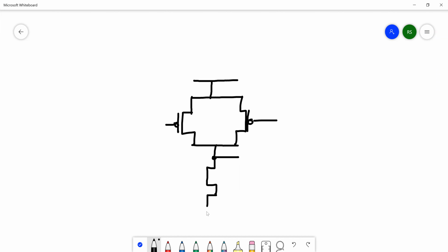If you look at this 2-input gate, for the pull down network, there are a total of 2 capacitances. One is the load capacitance, or what we call CL, which is the sum of the diffusion capacitances connected to the output and maybe some other gate capacitance. And one more is this intermediate capacitance.